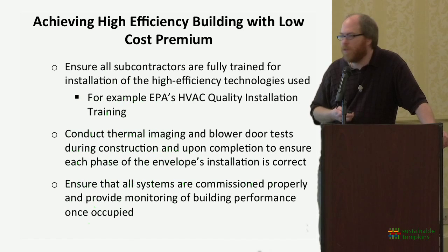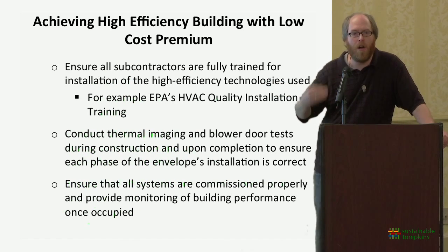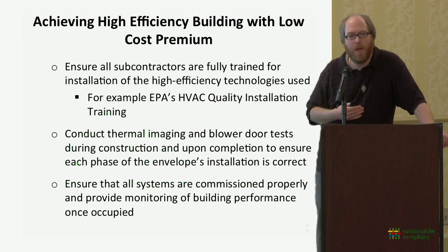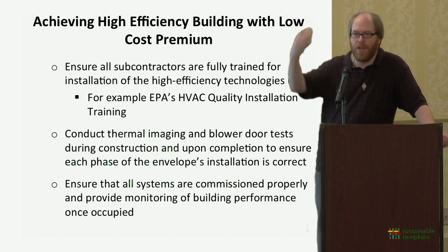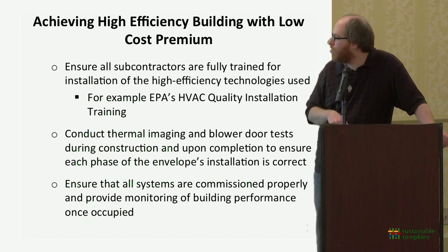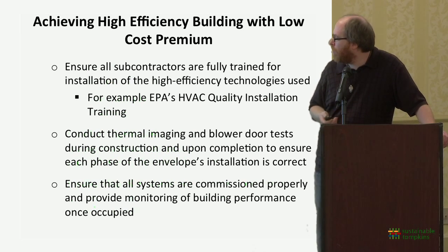We'll talk about those as well. To conduct thermal imaging and blower door tests along the way. That way, if you find problems with the envelope, you can fix them before all the finishings have been added and you're trying to do these at the end. Again, the sooner you can make changes in each phase, the better it is for the overall cost.